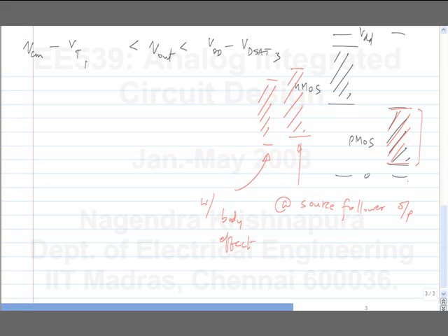Then use a PMOS source follower. What's the difference then? The only thing is the body effect will be gone, that's all. Still, it is a small range that is limited to the output range of the voltage follower, the output range of the differential pair. If you use a folded cascode which has a larger output range, it still doesn't help. Then it will get limited by the source follower.